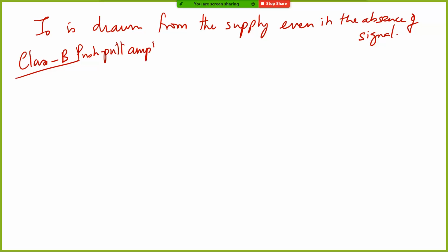I'll explain these terms, why they are called so. Of course, we know that emitter followers are the ones which help us. So what I'm going to do is, I'm not going to bias this transistor. I want this transistor to conduct only in the positive half cycle.